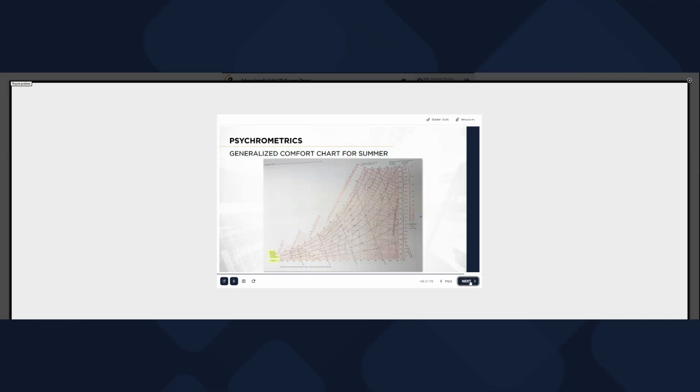This is a generalized psychrometric comfort chart for summer. Dry bulb at the bottom of the chart is regular dry air temperature. Specific humidity, the amount of moisture in the air, is listed on the vertical axis on the right. Specific humidity is measured in grain units. Wet bulb, dew point, or saturation temperature.